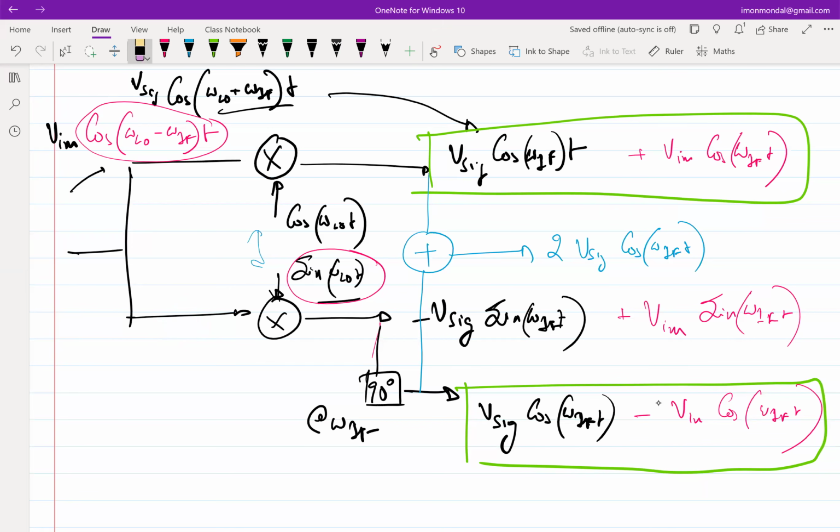Alternatively, if digital, this is at low frequency anyhow, right? Omega_IF is at lower frequency, let's say a few megahertz. In that case, you can directly put an ADC and you get everything in digital bits. When you have digital bits, then everything is math after that. Then you do your signal processing in digital. That is another option, but it all depends upon what the requirement is.